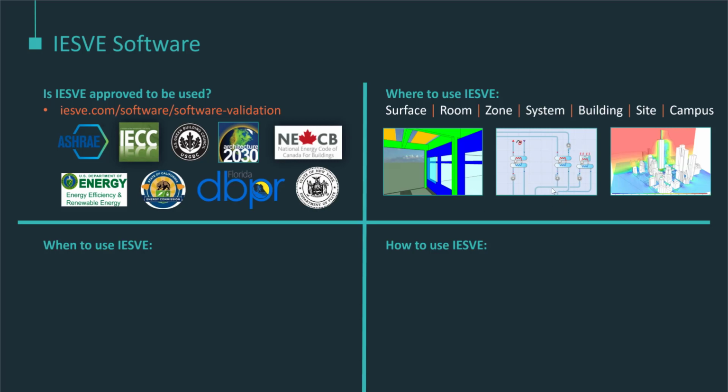So I'm showing a mechanical system here because in this scenario, you're actually not modeling any building geometry. You're just taking a building demand, so that might be a time series demand, and doing analytics on it. So you might be saying, what happens if we have a water-cooled chiller versus an air-cooled chiller? What happens if we have a heat recovery chiller? What happens if we move from a primary secondary loop to a variable speed drive on the primary only?